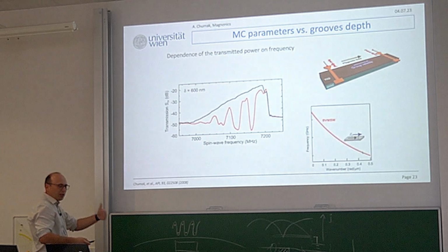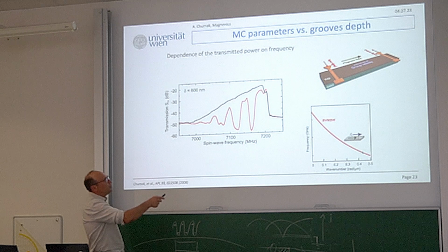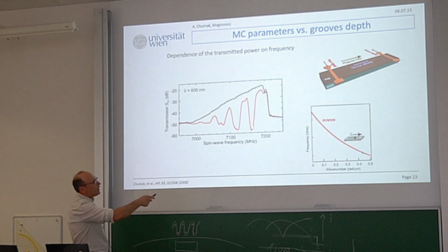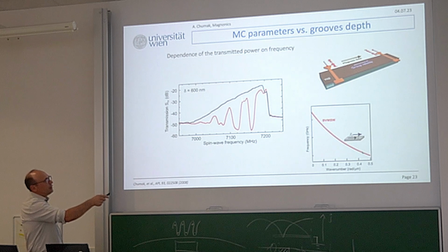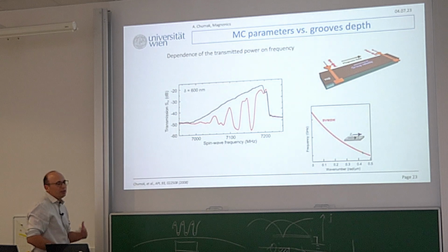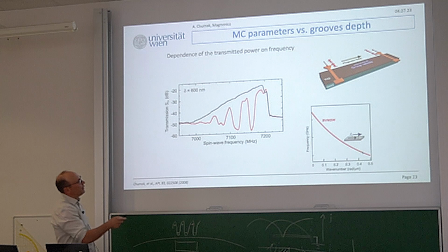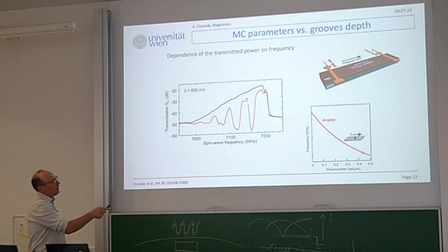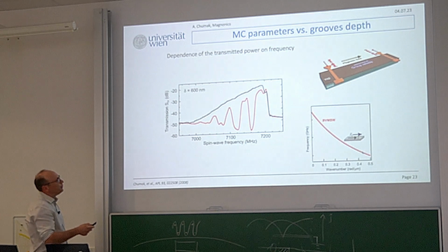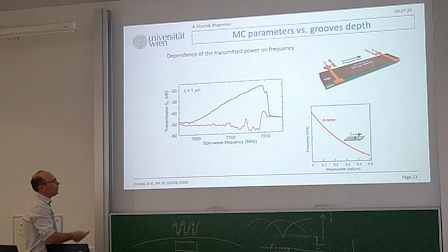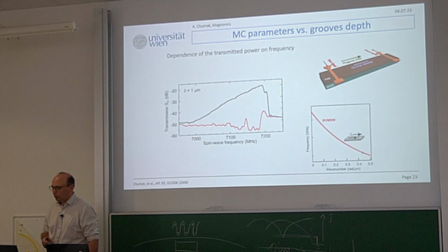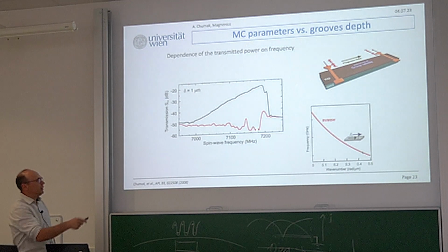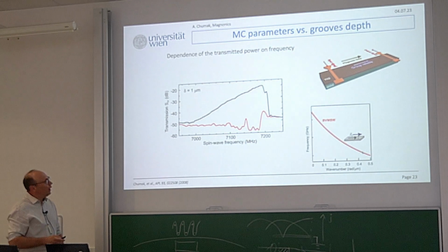So the larger the depth of the grooves, the deeper the band gap, but also the parasitic losses increase. The width is actually defined by the reflection efficiency. And if you have 1 micron, which is only around 20% of the thickness of the waveguide, we have seen no transmission anymore, so more or less the YIG was killed.